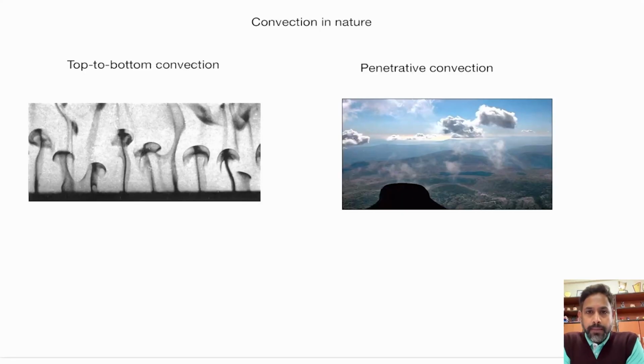So we have seen the reason behind convection happening in fluids, where we talked about thermal instability, and convection comes into picture when your Rayleigh number gets larger than a critical Rayleigh number, and that is when the system becomes unstable, where buoyancy force takes over the viscous force, right? And convection begins in a system, right? And we talked about critical Rayleigh number in different conditions.